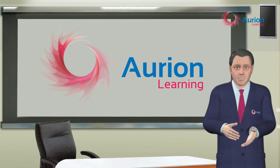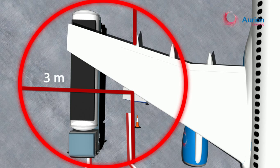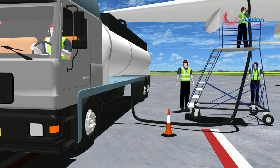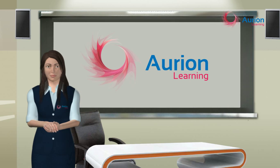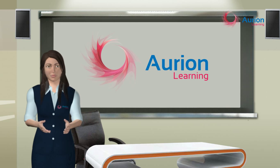Let us understand the fueling process. The fueling safety zone, which is an area extending 3 meters from the fueling point, the fueling vents, and the fueling equipment, is generally regarded as a radial area which is highly reactive. The fuel vent points are located underneath the aircraft wing, and this is where the potentially explosive fuel vapor is expelled.